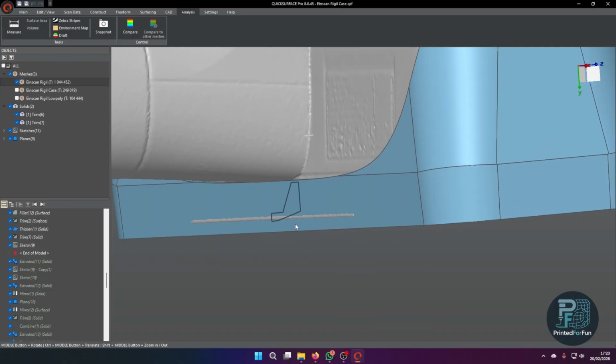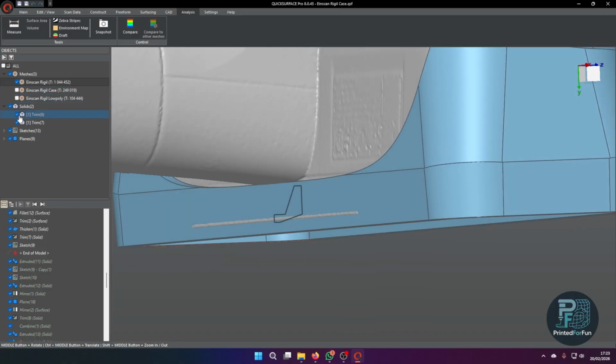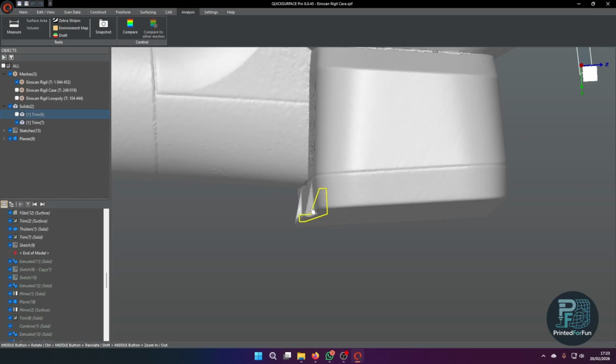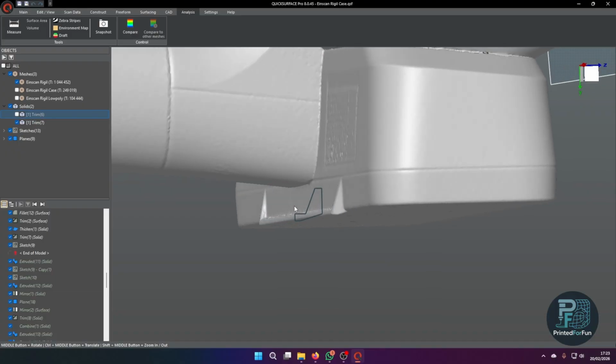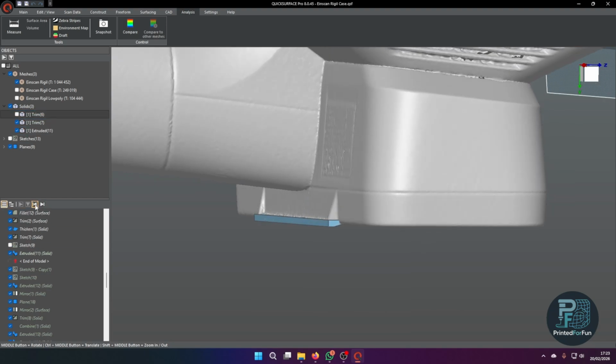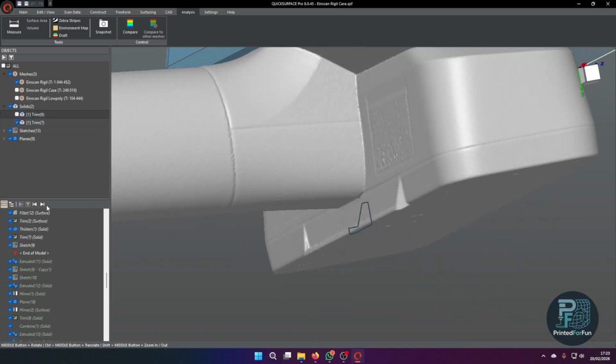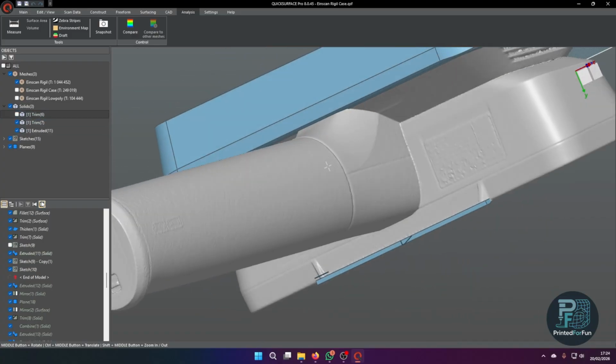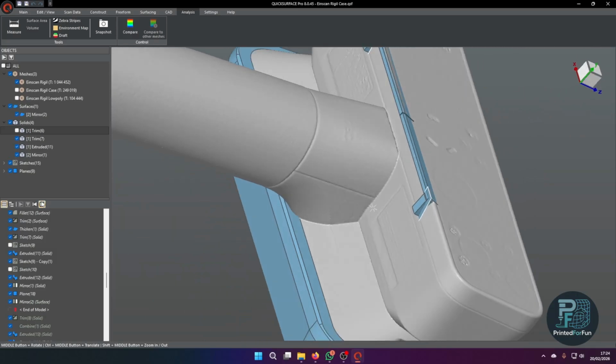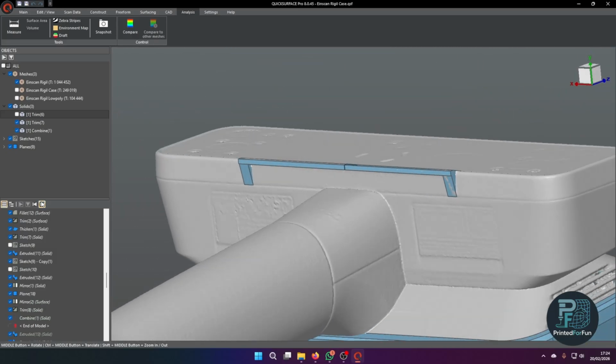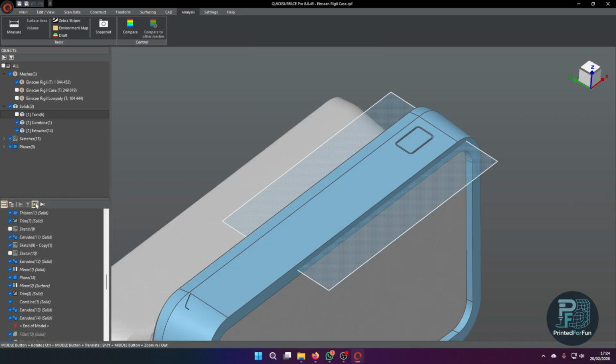The next thing will be a small cutout here for the lower lid, because as you can see, the scanner has this plastic rib used to protect the emitters when placing it down. The easiest way would be to clip it off or file it down, but of course I don't want to do this on such an expensive device, so I will create a cutout instead. And for this, I just again created an intersection sketch and extruded the sides, with a bit of tinkering around to create a good shape.